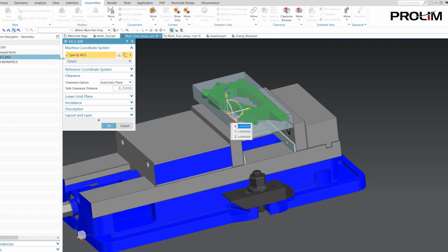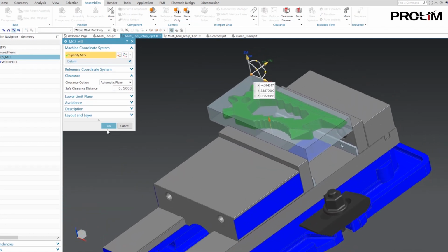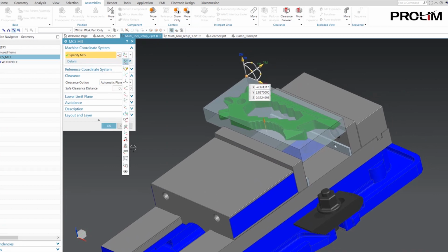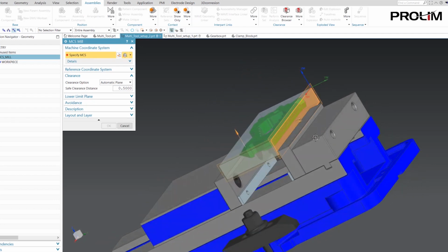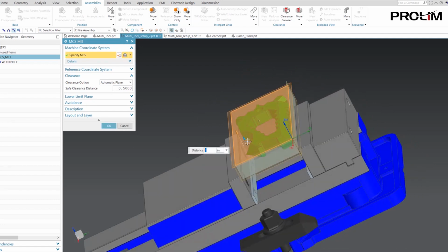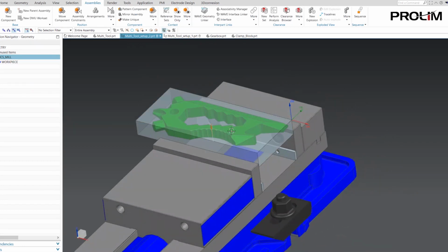For the MCS mill, now I can use the blank geometry again. I can just snap to points quickly, or I could easily use 3 planes and select an X, Y, and Z, and it'll snap to a plane quickly, or a corner quickly, or between 2 points. I can utilize the opposite corners to get the dead center of the raw stock for this part.